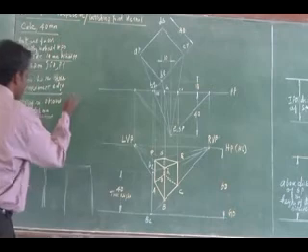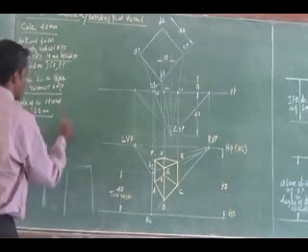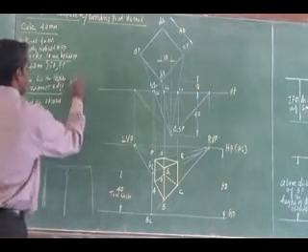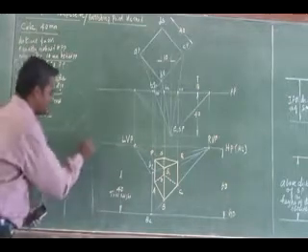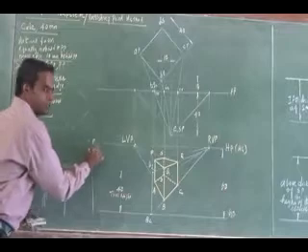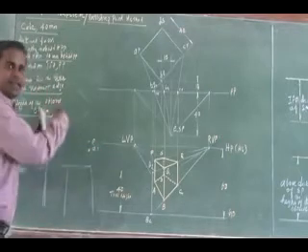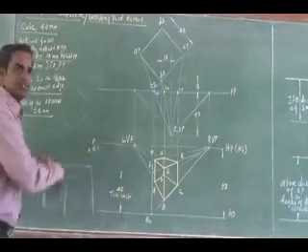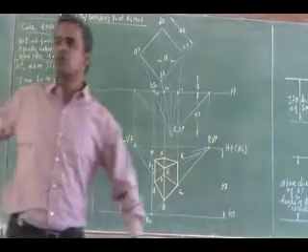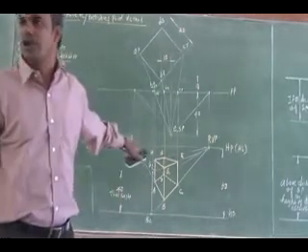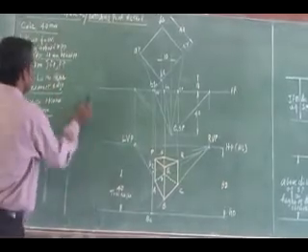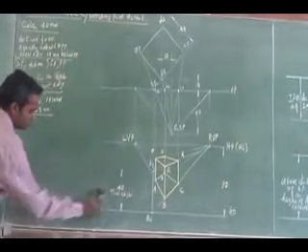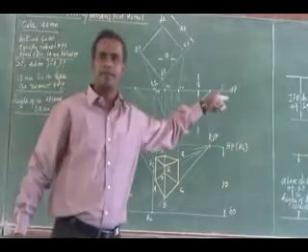And the top view will be like this, we have drawn already. Using the previous visual ray line, you can mark station point E dash, and you can project, get the intercept, and get the corresponding location of the perspective. Similar to the previous problem also, you can solve it. So this is 2-point perspective, which will give you a more realistic perspective view, since the faces are inclined.